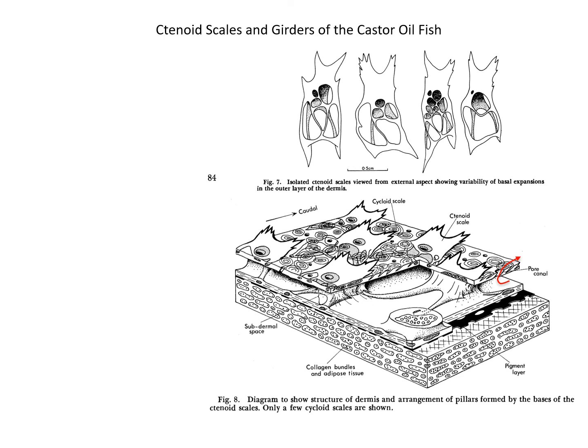So both of these devices, the sharp ctenoid scales that stick out, and then this very odd subdermal network of caverns, is probably an adaptation to keep the boundary layer attached. Those are a few adaptations to keeping boundary layers attached for animals that are working at high Reynolds numbers.